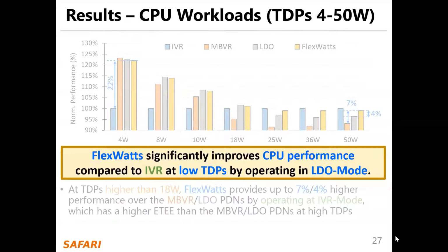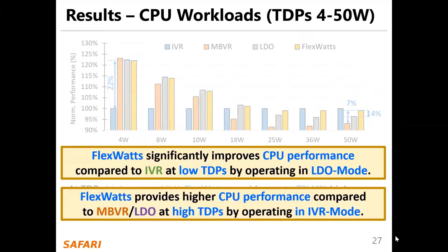FlexWatts significantly improves CPU performance compared to IVR at low TDPs by operating in LDO mode. FlexWatts provides higher CPU performance compared to MPVR and LDO at high TDPs by operating in IVR mode.